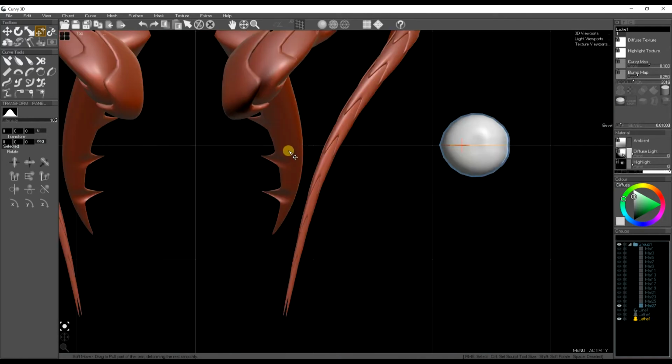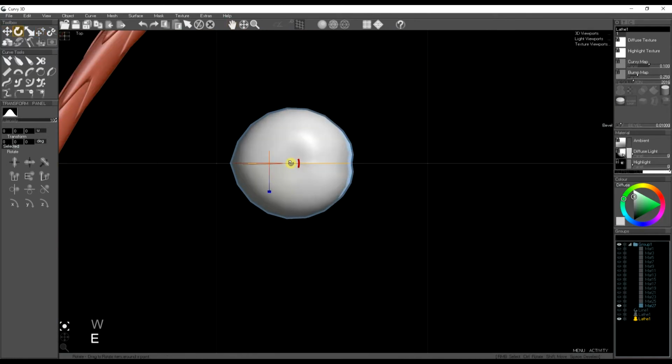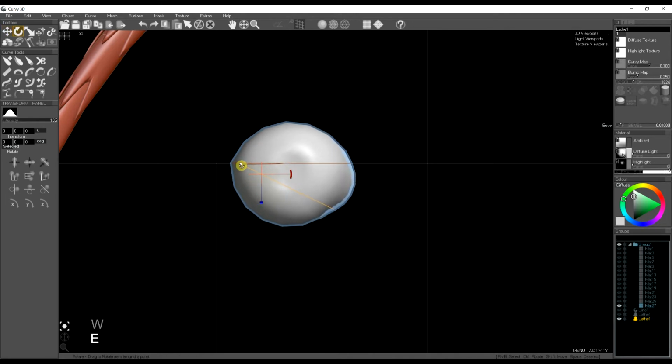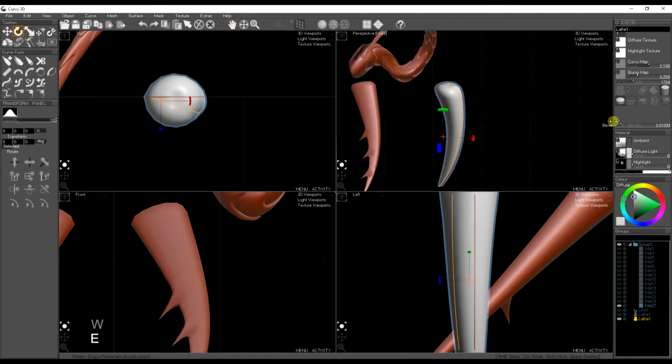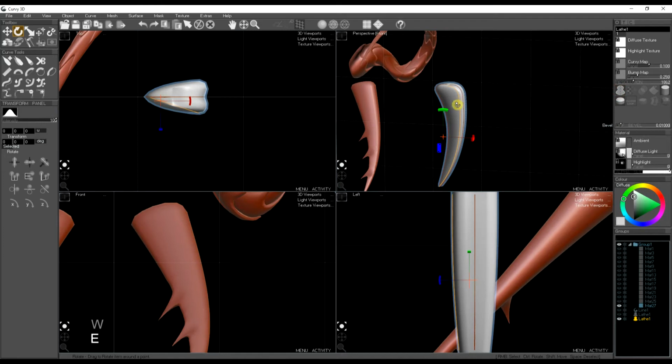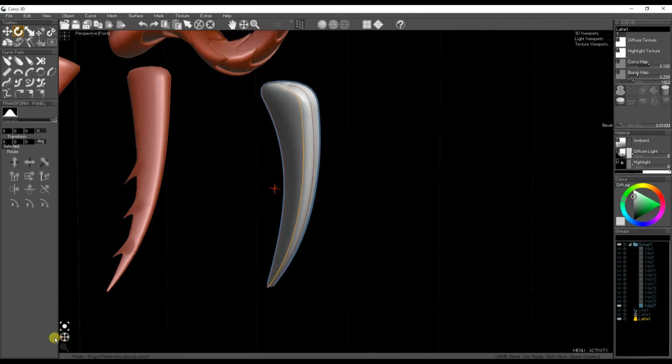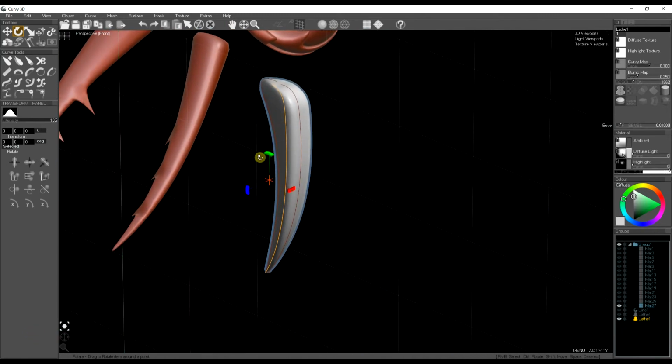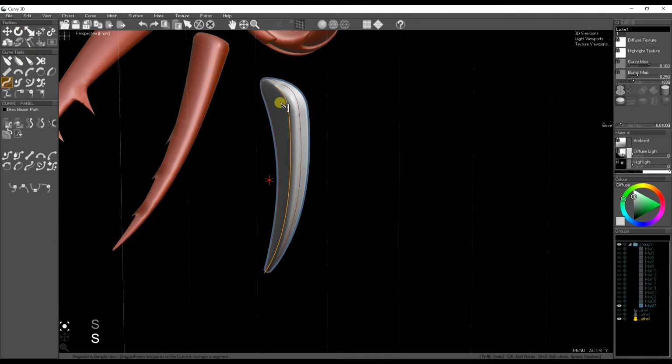Again, I'm going to use curve clone because we don't want this shape to be rounded, we want it to be quite flat. So I'm going to rotate the curve into place, but not 90 degrees, only a few degrees this time. And when I use lathe symmetry, it creates an almost triangular profile cross section. So we're making again quite a flat object. Smoothing that curve.